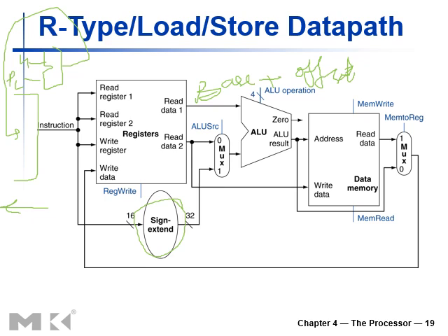So in that particular case, the second input is provided from this channel, and the ALU computes the physical address, and that address is being provided to the memory, and we're going to load the data from memory to the register. But for the R format instruction, we have to provide data from this line. So we have to set this ALU source control equal to 0.